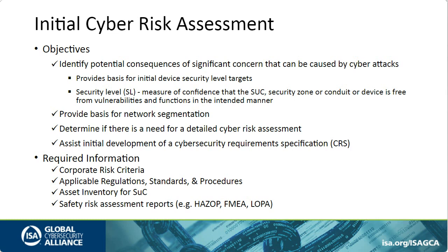There's a lot of other methodologies, but what you're looking for from your traditional safety risk assessment are the significant consequences of concern, and when you have those, what kind of safeguards you have to prevent those occurrences, and whether those safeguards are vulnerable to cyber attack or not.